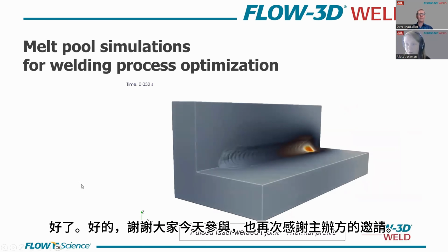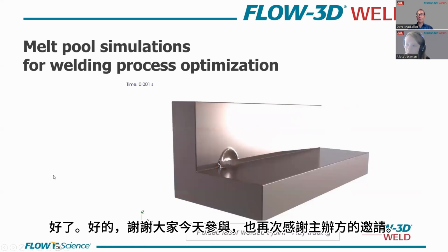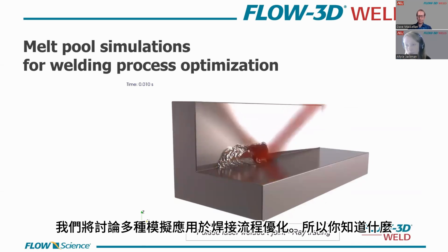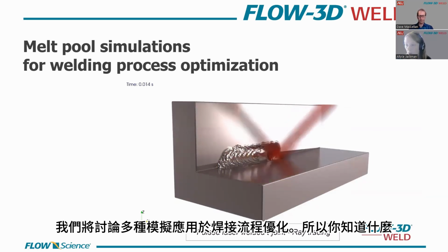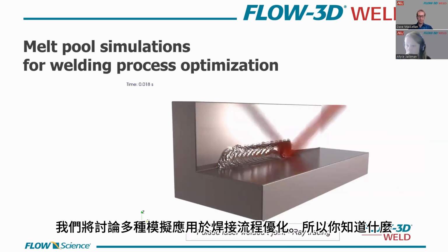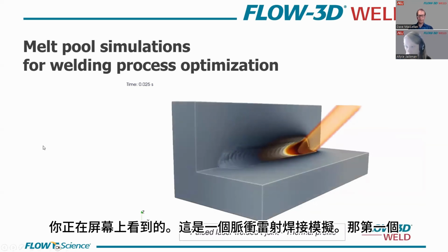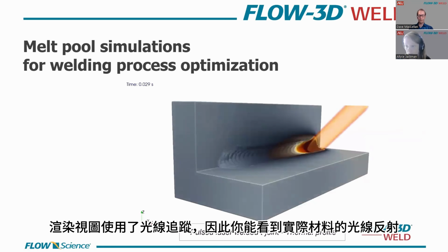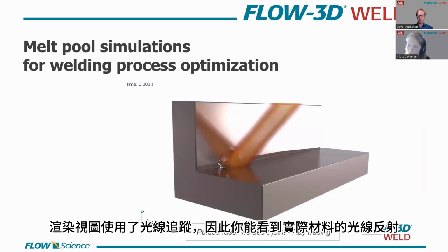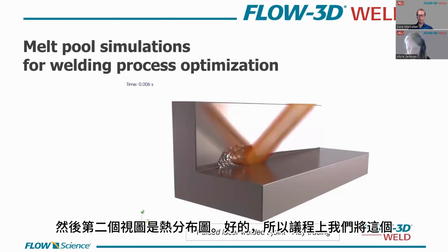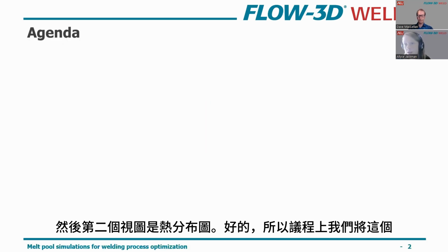There we go. Okay, yes, thanks for joining today, everybody, and thanks again for hosting us. We're going to talk about melt pool simulations for welding process optimization. So you know what you're looking at on the screen here, this is a pulsed laser welding simulation. That first render view was using ray tracing, so you get the light reflections from the actual material, and then the second view is a thermal profile.